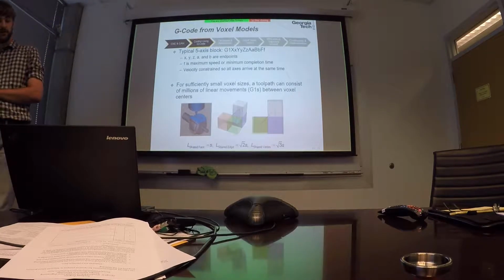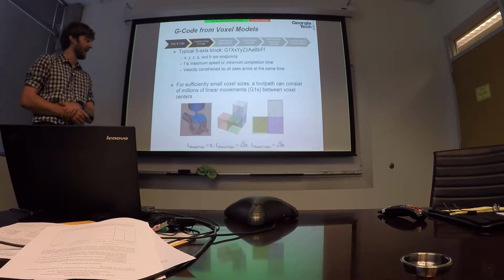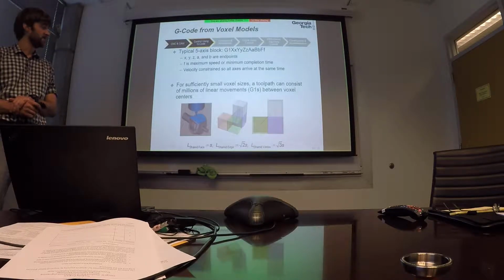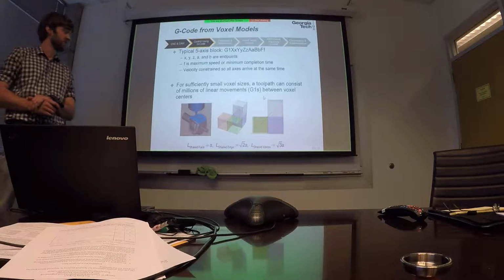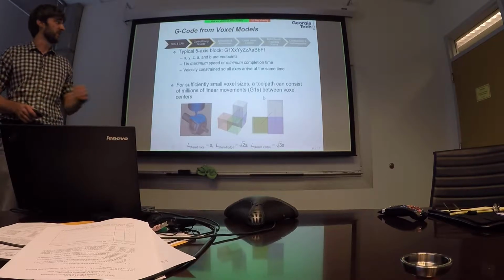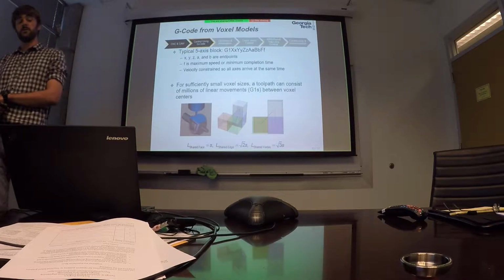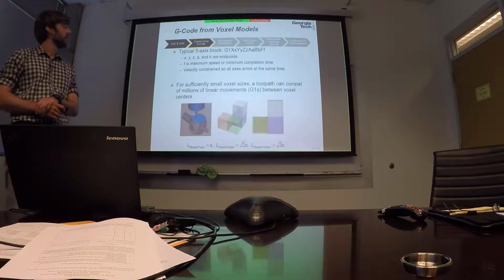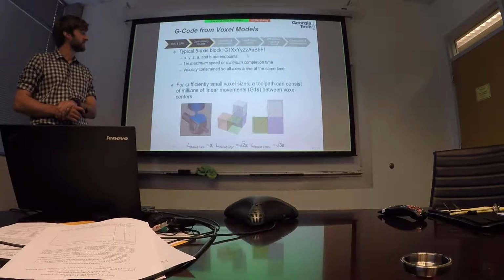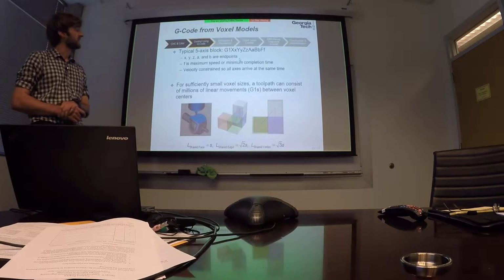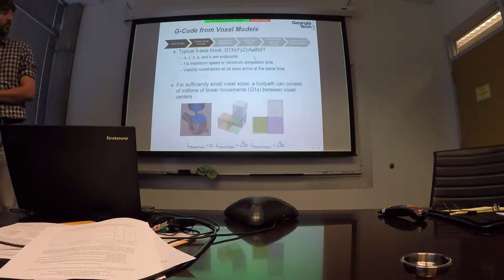So we're using GCode for parametric CAM originally. Here, actually, in order to use GCode for voxel-based CAM, there are some different considerations we need to consider. As we said, a 5-axis block, where a block is a line in a GCode program, looks like the one that you see here. So we have G1. G1 means linear interpolation, and capital X, Y, Z, A, and B are axis addresses, and then lowercase x, y, z, a, and b are move endpoints.